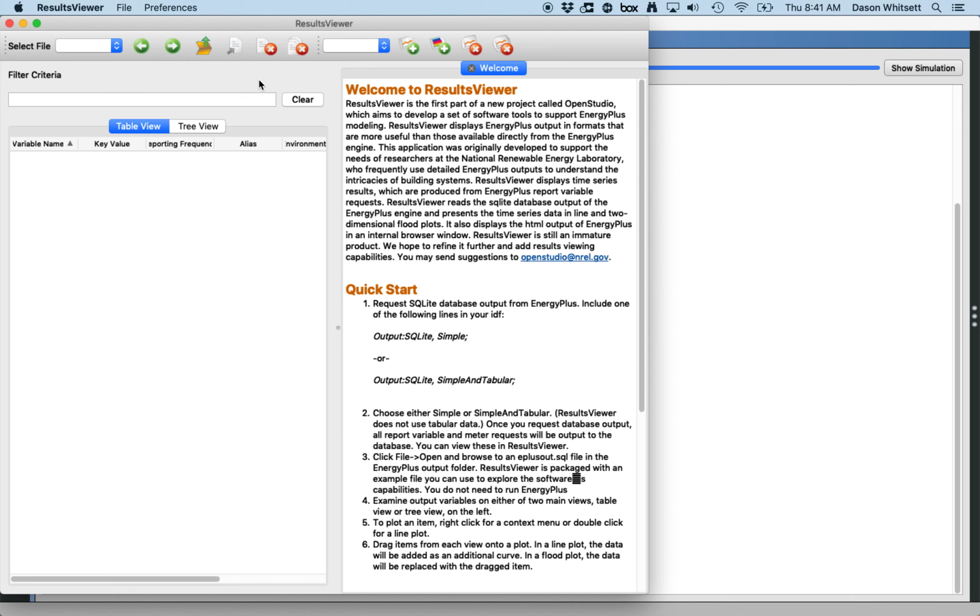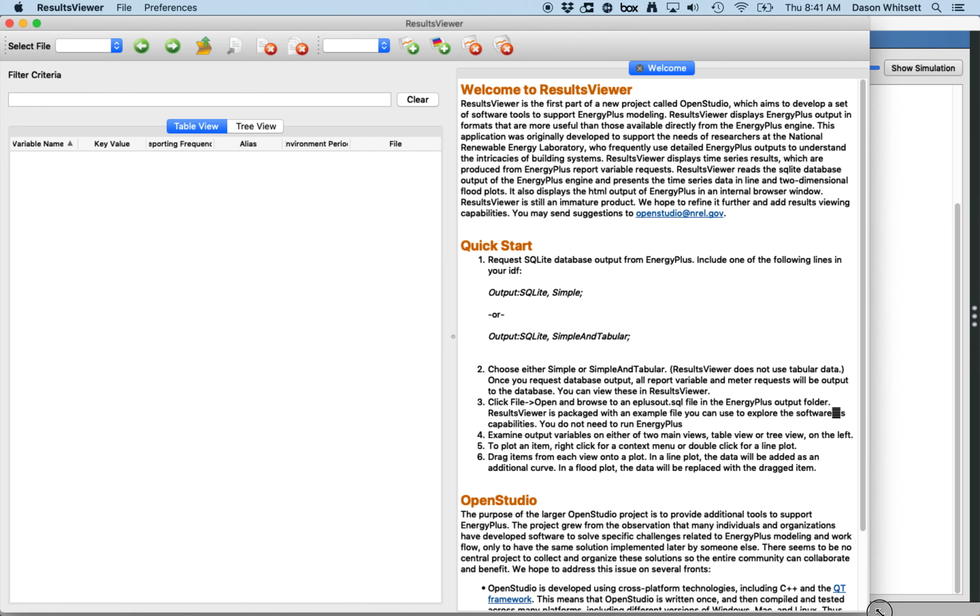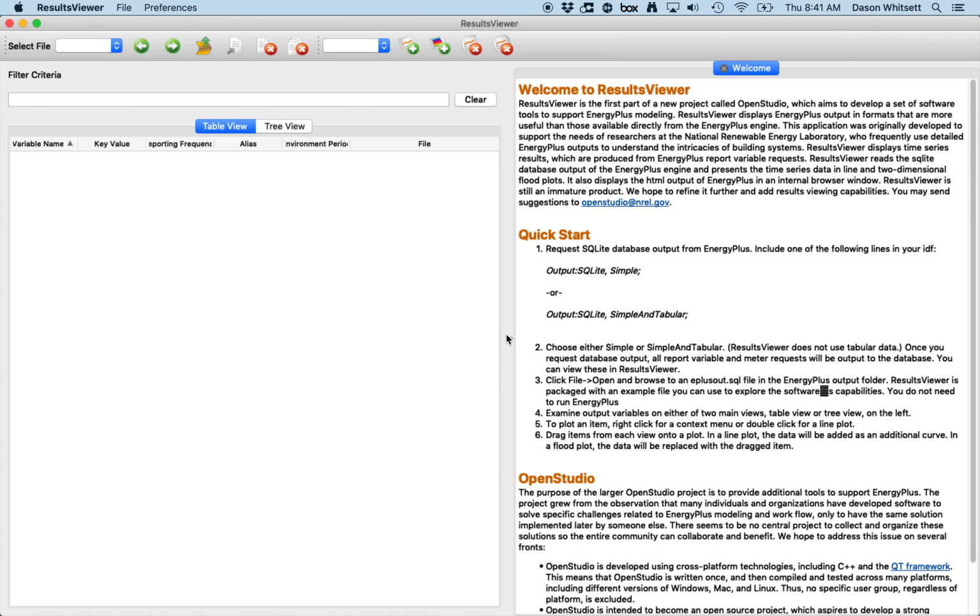I've uploaded the OpenStudio version 2.2 software installer on the Box distributed folder under Reference. You can install this, but all you need to install is just the results viewer component, not the entire OpenStudio package. Once you do that, you can open Results Viewer, and this has a key capability for daylighting that wasn't built into DView.